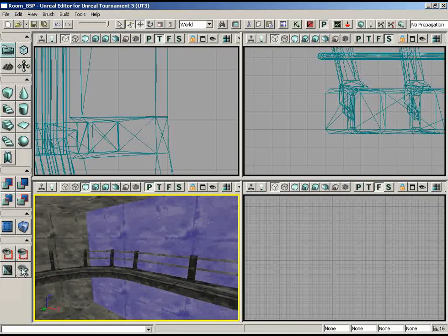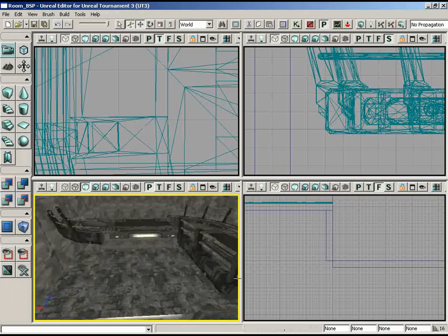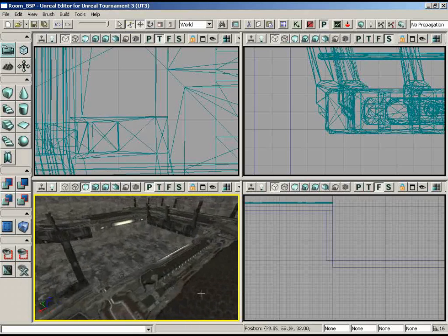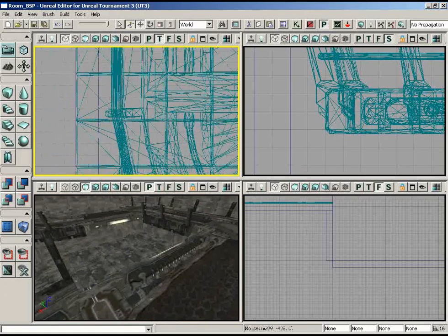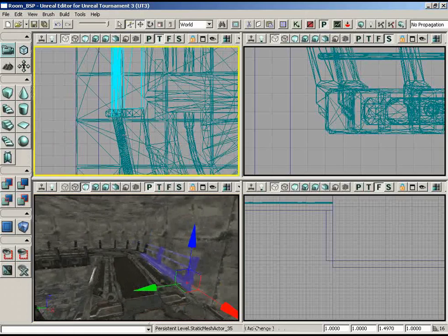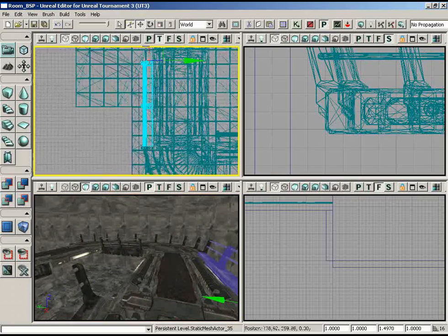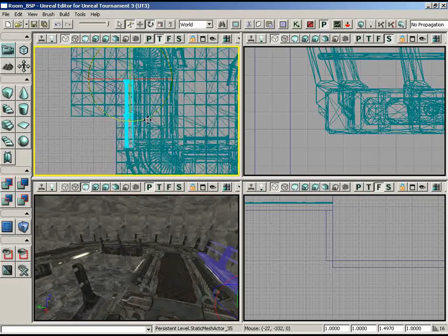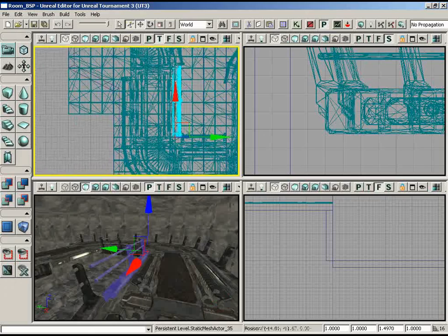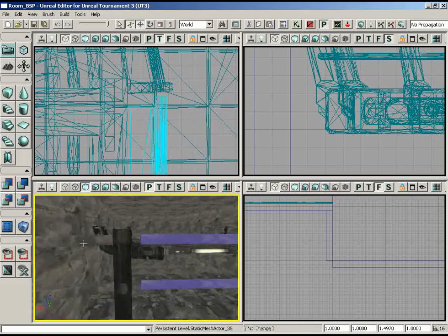Alright, let's bring all of the meshes back now, and let's see what's next for getting a guardrail. We could probably set one up on the other side. As a matter of fact, I wonder if we could just reuse that scale and move it over to the other side. We need this solid piece to be on the far end, which is fine, so we could just go into rotation. We could duplicate and rotate this around about 180 degrees and try to move it into place and just see how the length is working. This one might have to be a little shorter, but I won't know until I get it lined up.